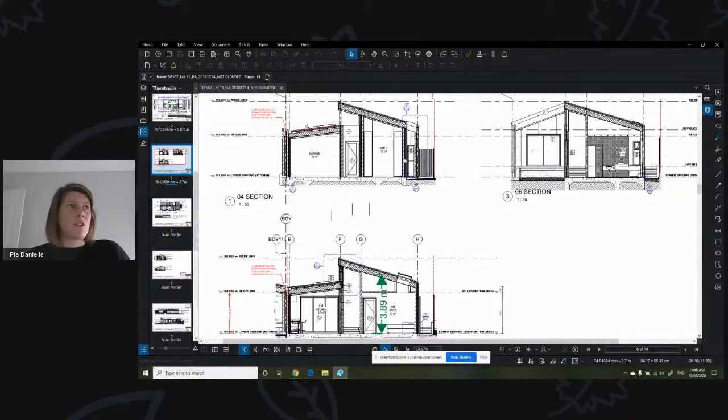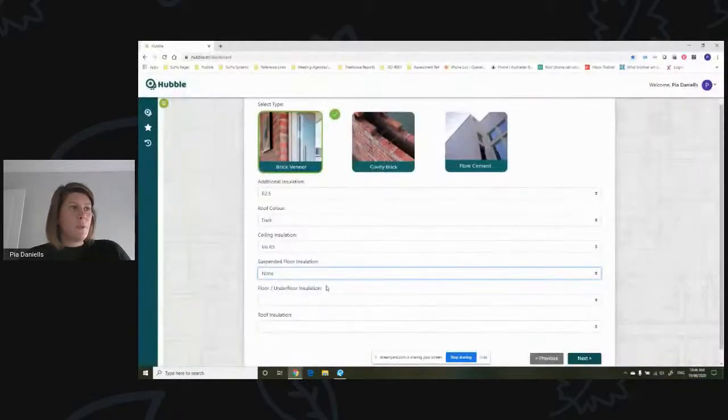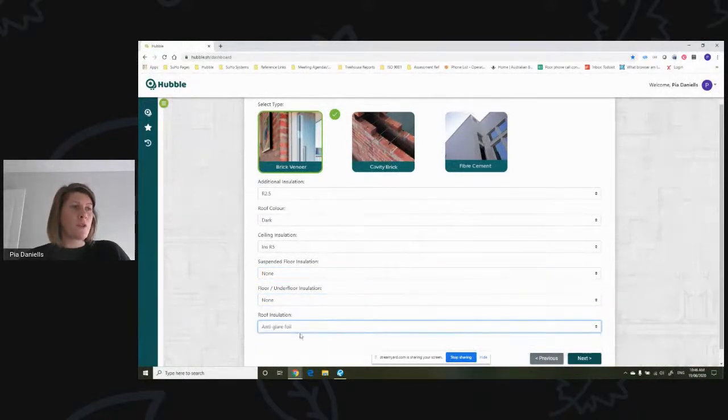There's the insulation, which is in the specifications, and the ceiling insulation here. So you can see the large ceiling batts and then batts further up here. So there's no floor insulation, and then we're just going to put some foil, which would have added insulation, which is being, as again mentioned, added to the system at roof level.